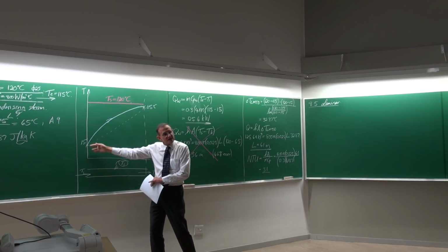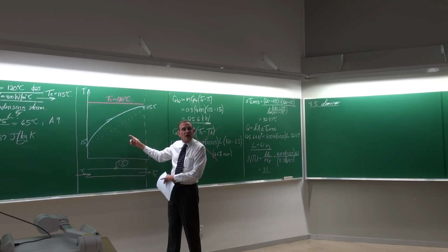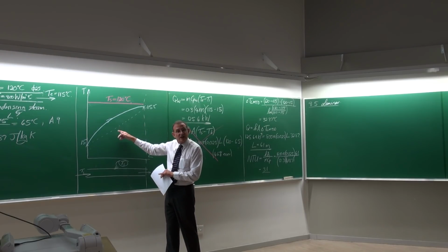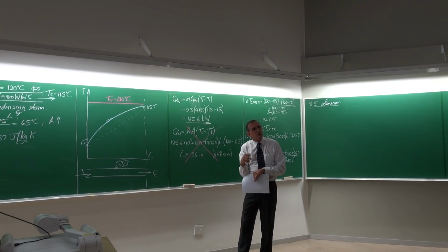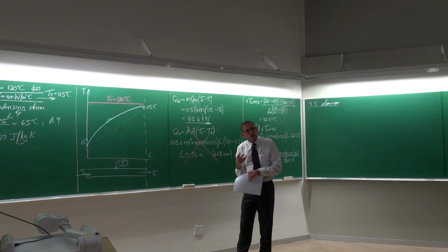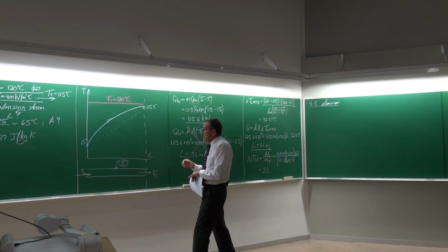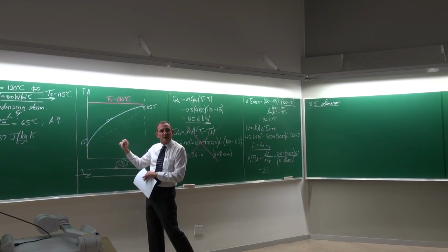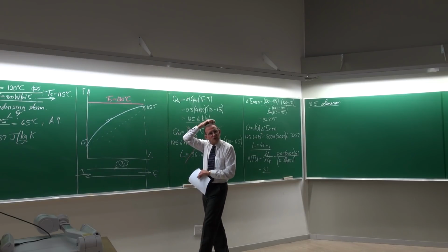Then you use 60 plus 115. You do the calculation, and then you get the new values, and then you just use that value to recalculate the bulk temperature. Normally, you don't have to iterate more than about two times, very quickly it will converge. In many cases, you'll see that we can typically even use that value, and it will still work out fine.